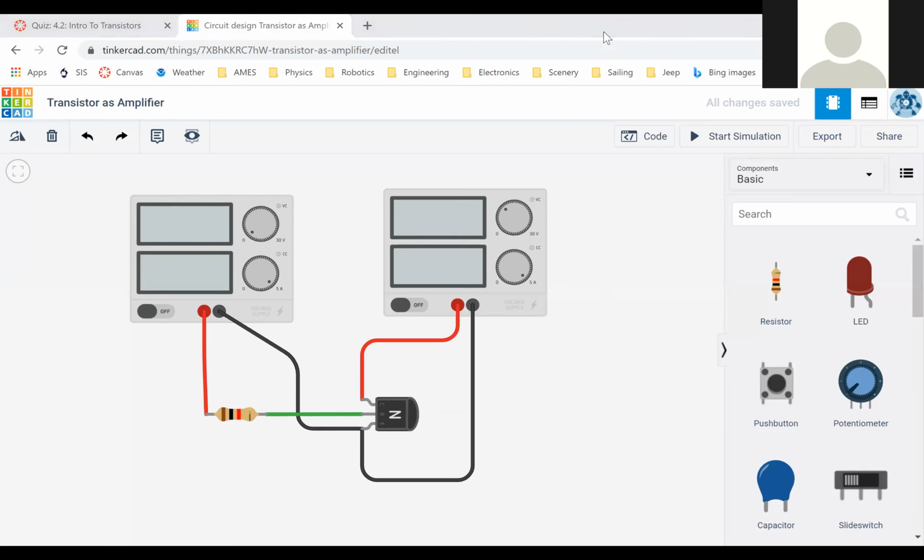You should have a transistor, which you have got hooked up so that we've got a power supply here, and we got some voltage that comes into the base. So that's the base of the transistor, right? And we've got a resistor here. So the resistor limits it so that we only have a slow trickle of current coming into the base. But that's all we need is a slow trickle.